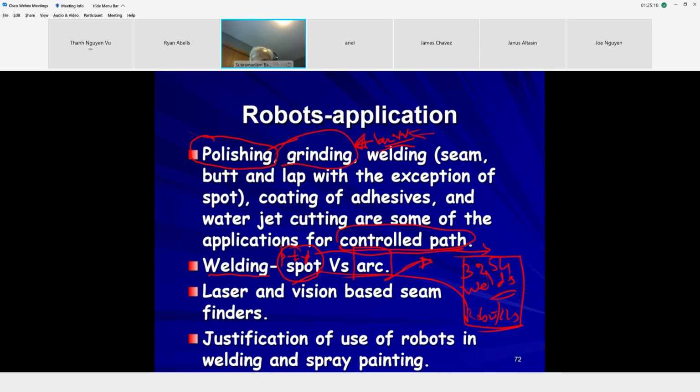Could be curved, could be straight line, where you are doing a seam welding between the two surfaces. If you have done spot welding, you don't do spot welding with hand, you take the spot welding gun, just apply heat and point. Whereas in seam welding, you got to take the gun and go along a line or an arc. Weaving. Weaving is important.